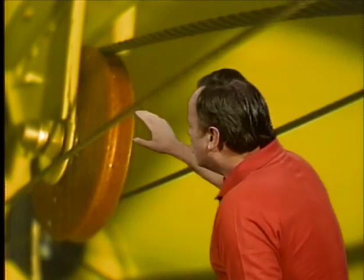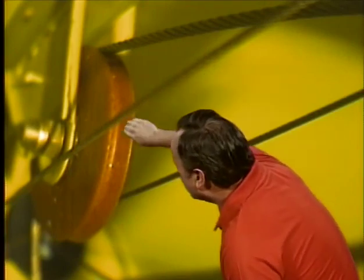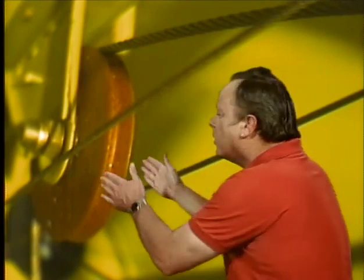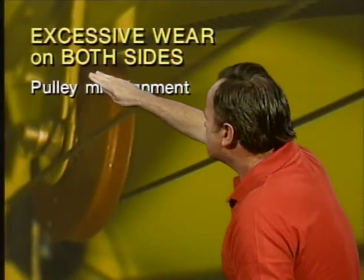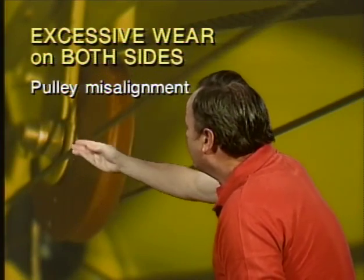Now, let's assume you're out in the field as a working mechanic and you are inspecting a control cable pulley like this one right here, and you check the pulley groove and you see excessive wear on both sides of the groove. Now, you look in here and you see a lot of wear inside that groove on both sides. What would that tell you? And the answer is it would tell you that you have pulley misalignment. It's not lined up properly. So excessive wear on both sides of the groove of a control cable pulley would tell you that you have pulley misalignment.